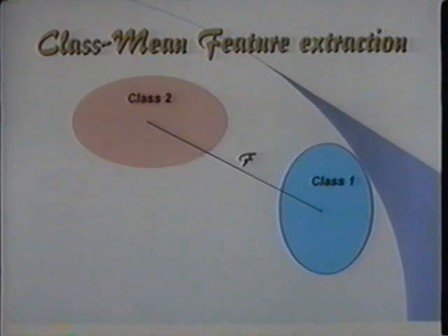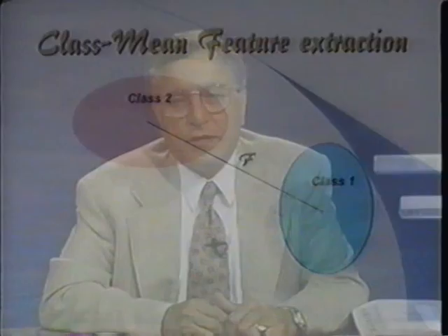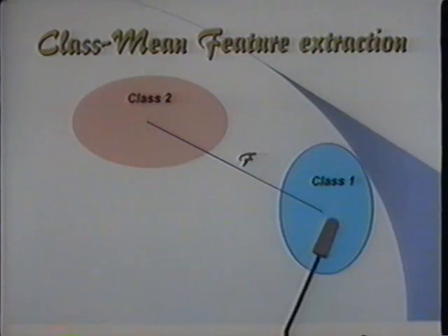If you take another variable, for example, a load in a very remote area and it's a very small load, and you find that if that load is 100% or 0%, it is not going to make any difference in the security status, then that particular variable is not going to separate the two classes, and you should not have it in your data to start with. Including that in your data will actually have a negative impact on the training of the neural network. So what we're looking for here are variables that can create a big separation between the two classes.